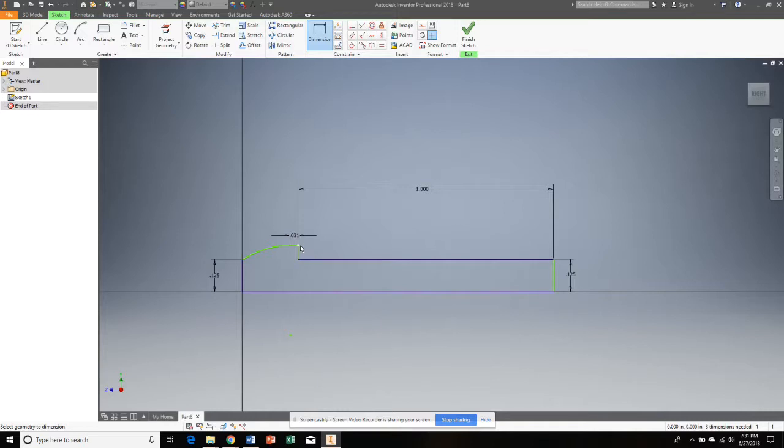And then we need to figure out what is from here to the center point. And this is that large shoulder. What is its diameter? And so we're actually looking for the radius. The diameter, if you look on here, is 0.422. So I'm going to say 0.422 divided by 2, which is 0.211. And that's really starting to look the right shape.